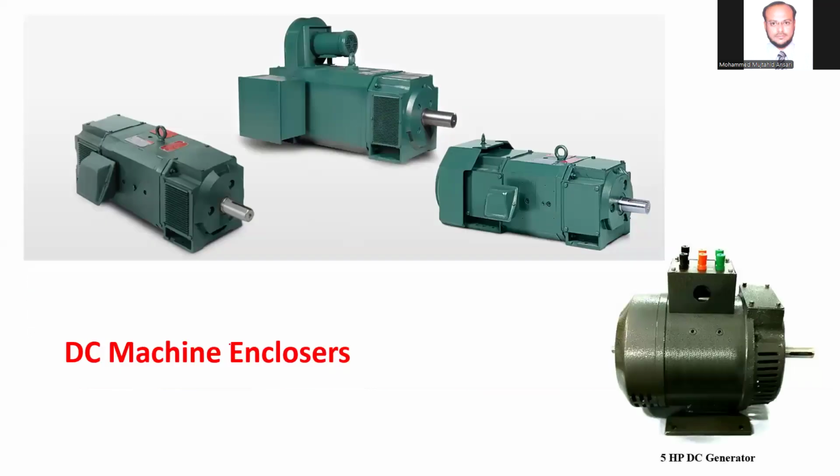Now these are the enclosures. There are different types of enclosures. Some vents are provided for cooling purposes. But if these vents are very much open, we cannot use such a generator or motor in dusty areas like cement factories, or where dust and dirt are there, or place it outdoors in the atmosphere. So we have to use a machine which is totally enclosed.